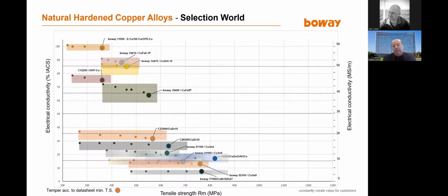I have made the boxes around the alloys according to the temper ranges from minimum to maximum, as well the ranges you might find in conductivity. So therefore, some box is a little thicker or the other one is a little thinner in gauge. And I think the key point in order to judge an alloy is you combine or you see the hardest temper. These are the big, thick spots. The smaller spots are the ones which are, let's say, other common tempers.